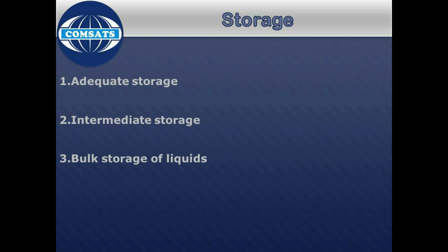Bulk storage. Bulk storage of liquids is generally handled by closed spherical or cylindrical tanks to prevent the escape of volatiles and minimize contamination. Liquids with vapor pressures above atmospheric must be stored in vapor-tight tanks capable of withstanding internal pressure. If flammable liquids are stored in a vented tank, flame arresters must be installed in all openings except connections made below the liquid level. Gas storage.